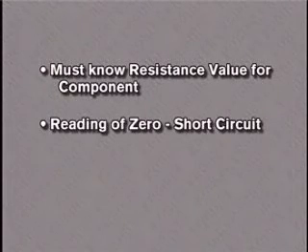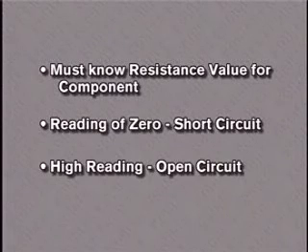If a component is being tested, you will need to know the resistance values for the component to make an accurate evaluation. Ohm meter readings of 0 ohms could indicate a short circuit, while very high readings could indicate an open circuit.